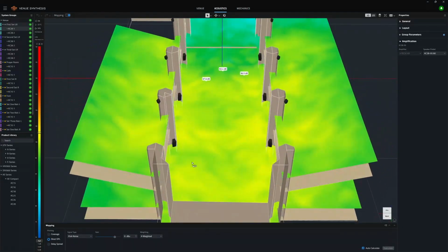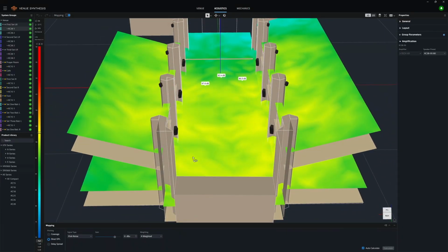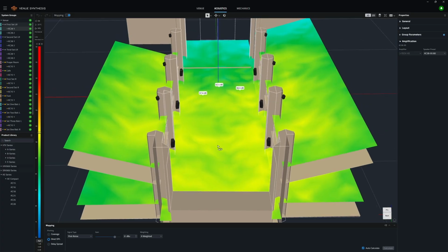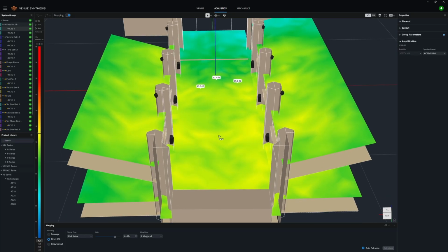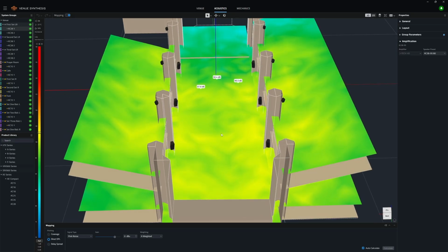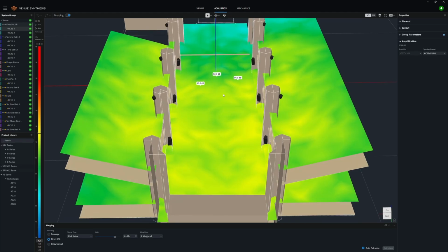So then the only things we've got left is we've got 3 channels left of that amplifier for 1200 watts. And we still need 6 channels total, plus 2 subs. So all in all, we might be sticking in maybe 2 more amplifiers of the same. So as a reminder, these are 750 watt program, and it'll be basically using singular channel rather than adding them together, so then we can actually delay them properly down the room.